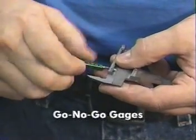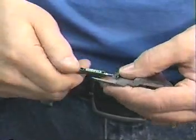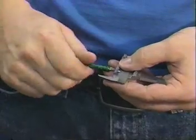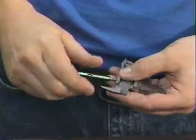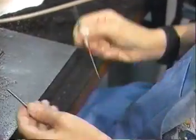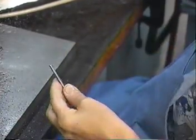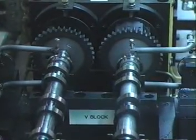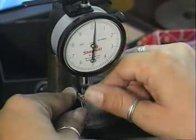Go-no-go gauges are used to ensure part features are within proper tolerances. Typical go-no-go gauges have accurately sized ends, one within tolerance called the go end, and one outside of tolerance called the no-go end. For a part to be acceptable, the go end must fit, but the no-go end must not. There are numerous types of standard and custom-made go-no-go gauges used in manufacturing, many incorporating graduated scales.